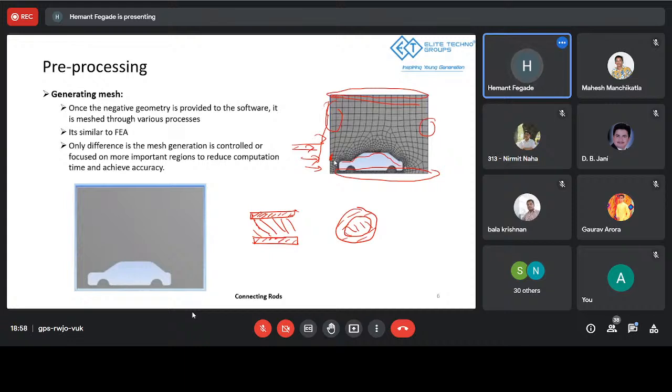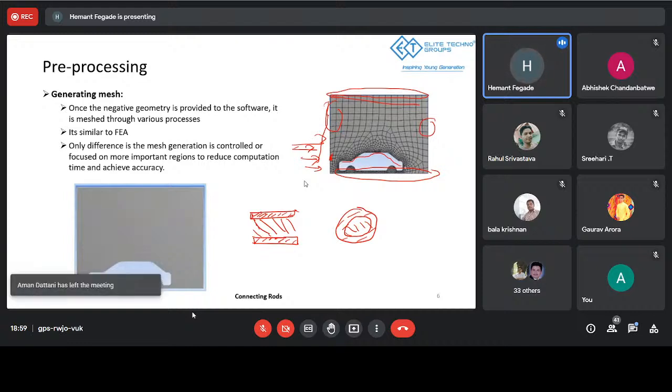So what we do is, we don't give the speed to the vehicle, but we give the speed to the air that is going to be impacting upon the vehicle. This is the analogy that most CFD concepts use, so that your object is stationary and your air is moving over the object instead of keeping the object moving. Because if you keep the object moving, it becomes time dependent. But over here you can actually run a steady state analysis if you give the velocity to the air.